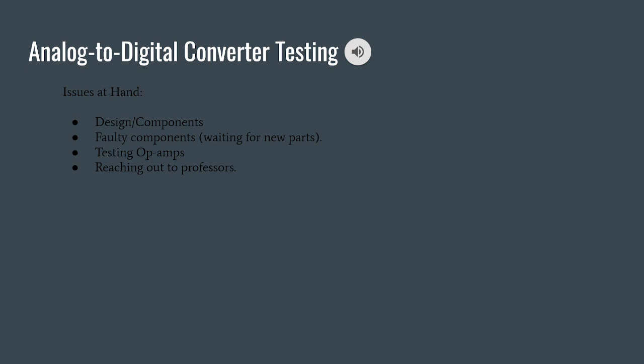to be way more distorted than desired. As well, in the beginning testing stages, the op amps were tested without a bypass capacitor to the power supply, which also could have been the extreme source of oscillation to our output signal. We are trying to get this solved within 1 to 2 weeks and have received help from outside sources to get this done.